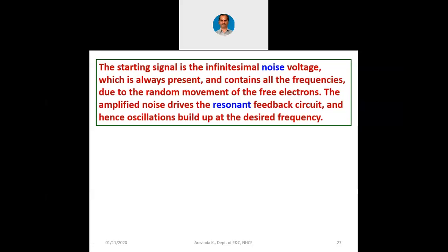That means initially it will be off only. To turn on fully, it takes a finite time. Now, when the transistor takes that finite time, there is always movement of electrons within every material. Inside the transistor, as it is a combination of many junctions, in the case of BJT, there are collector to base and base to emitter junctions.